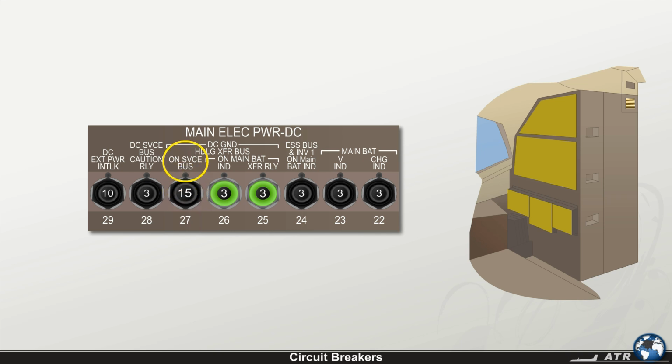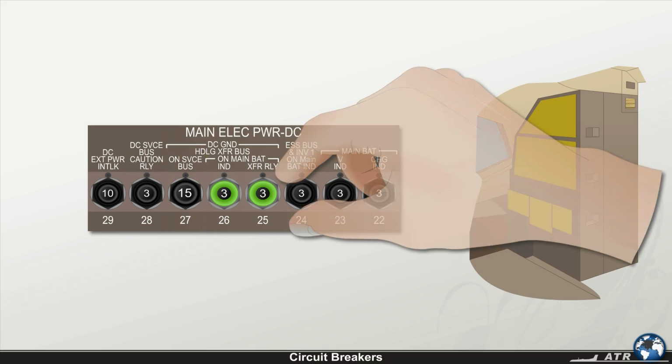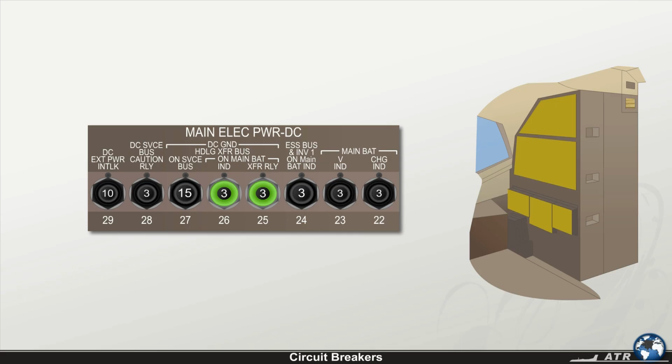which system is affected. All circuit breakers can also be manually pulled out at any time, thus isolating the respective electrical circuit. Some specific circuit breakers, such as the ground handling bus circuits, are fitted with plastic rings to enable the crew to quickly identify them as ones that have to be manipulated during normal operation.